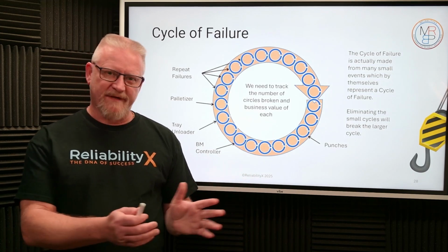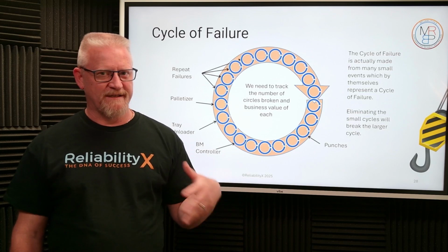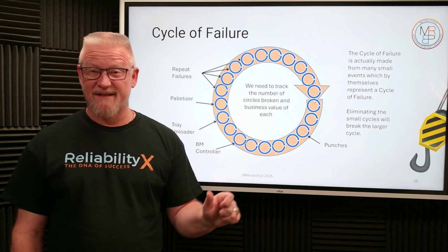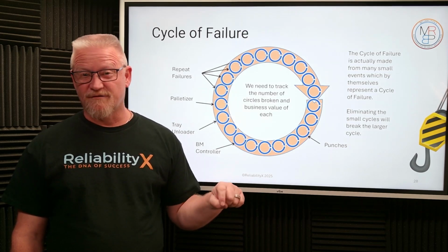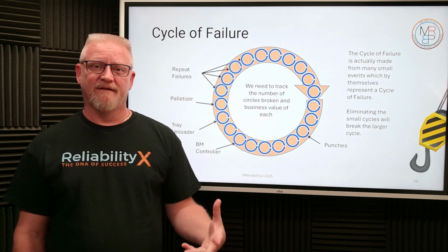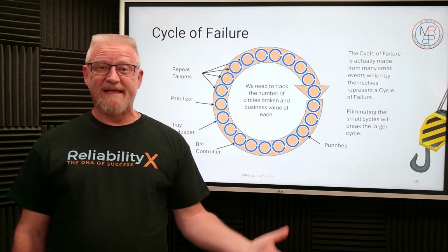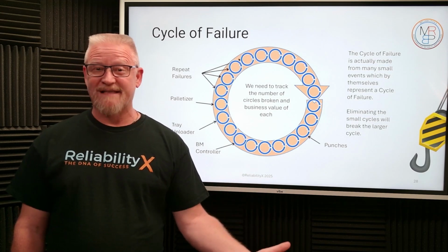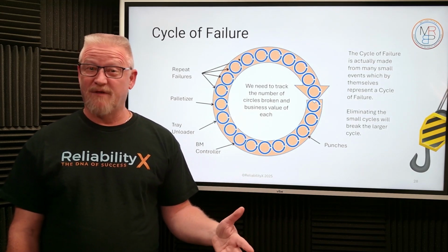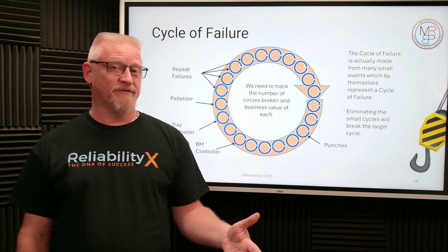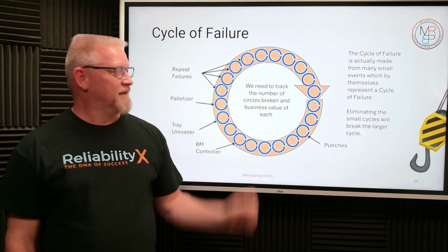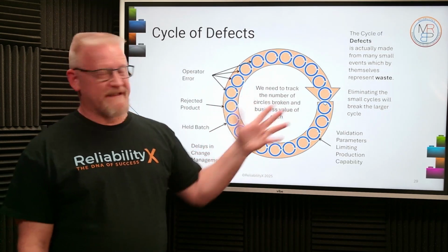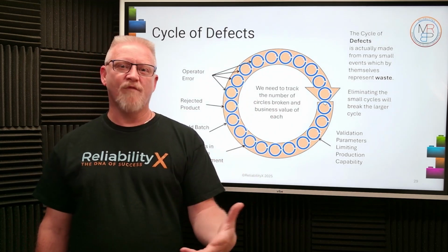If we have problems because things get adjusted that shouldn't be adjusted, fix them. Make sure they cannot be adjusted. Oftentimes we see sensors that get bumped because they're installed with one screw and not two. That's a defect. Weld them in place so they can't be adjusted. Use two screws so they can't be adjusted or are less likely to get bumped. Put them in places where they are less susceptible to being bumped physically. Eliminate the defect forever. If we can eliminate that cycle of defects, then we start to become more reliable in our operation.